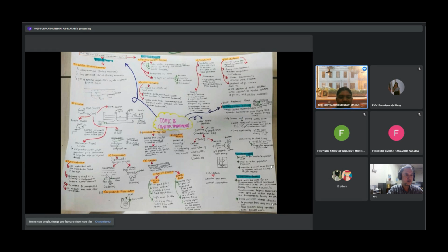The second one is about water quality standard. It's a guideline according to WHO and Ministry of Health. The third one is design criteria in water treatment system: plant location factors, design basis, environment factor. At the end of the chapter, I have a calculation regarding chlorine and alum dosage.